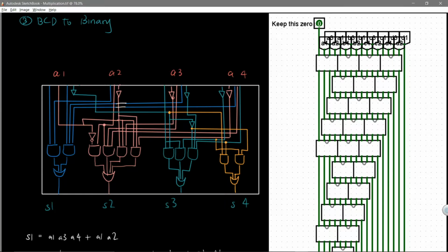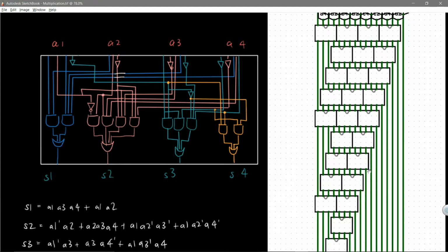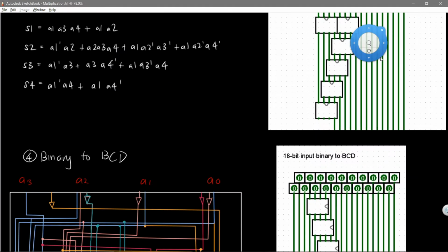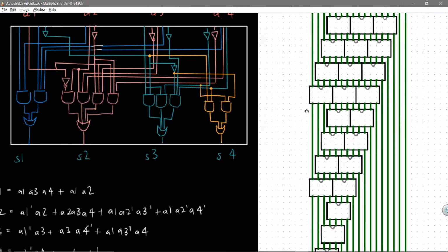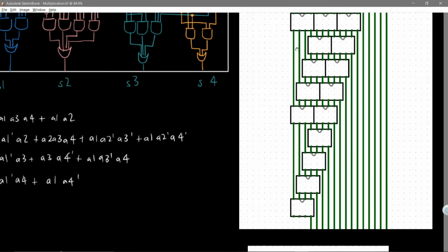So you just connect a 0 input here, and you don't need to change this input. Alright, this is how it looks. Then it's just connecting the chips here, connecting the chips here, and each layer you shift one bit, just move all the way down to be the output value. Alright, so all the way until you connect to the end of the sequence, and this is actually the 0 input here.